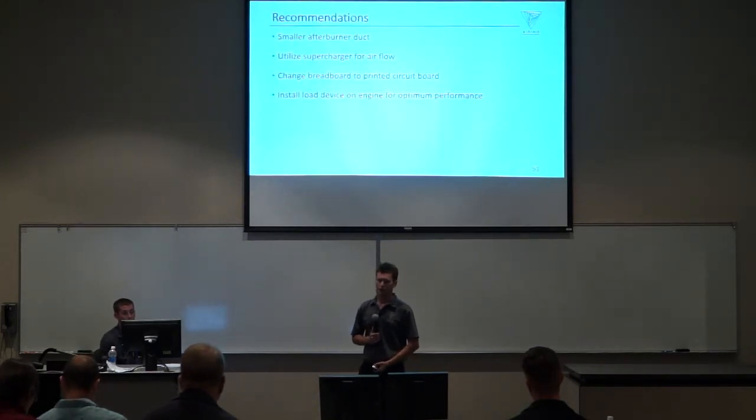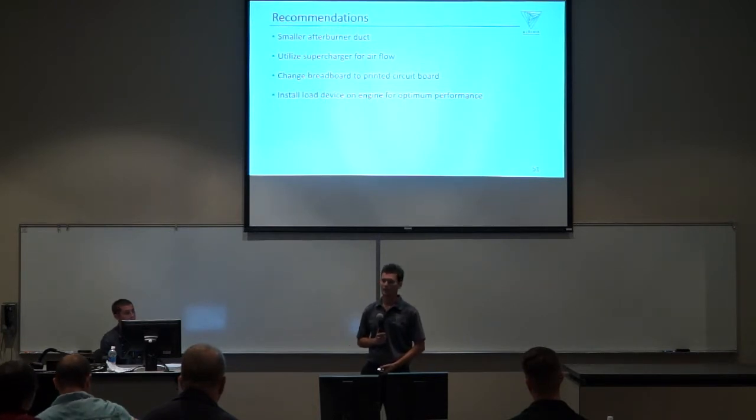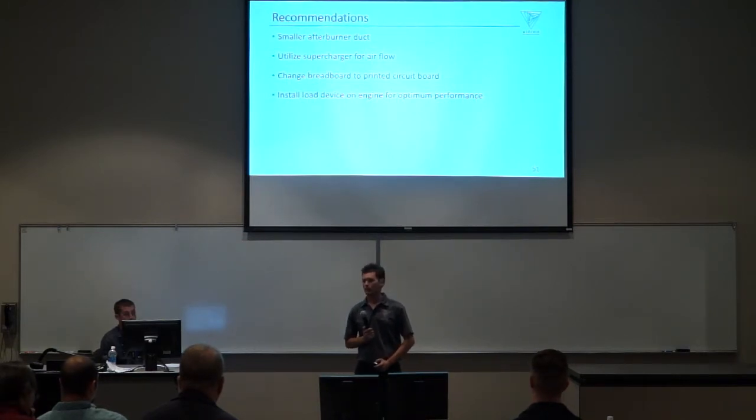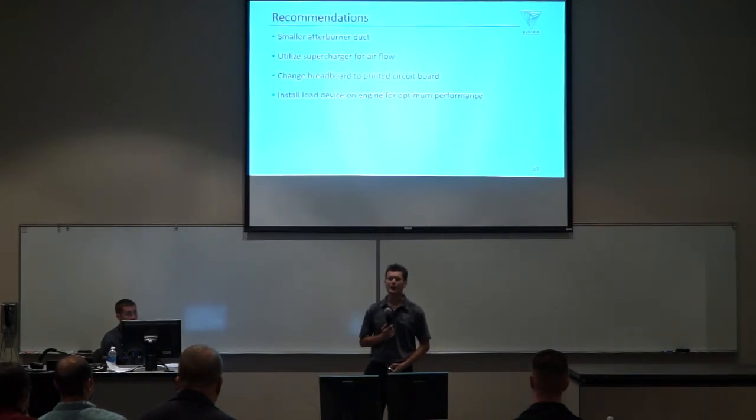Going further in this project, there are a handful of iterations we would do had we had the time and money. First being a smaller afterburner duct, we would decrease the diameter of the combustion chamber. To give you an idea, the Ford 7.3 liter Power Stroke is approximately a 444 cubic inch motor. That's what this turbo was designed to fill. This afterburner duct we've created is 26 inches long, 5-inch diameter. It comes out to about 511 cubic inches.